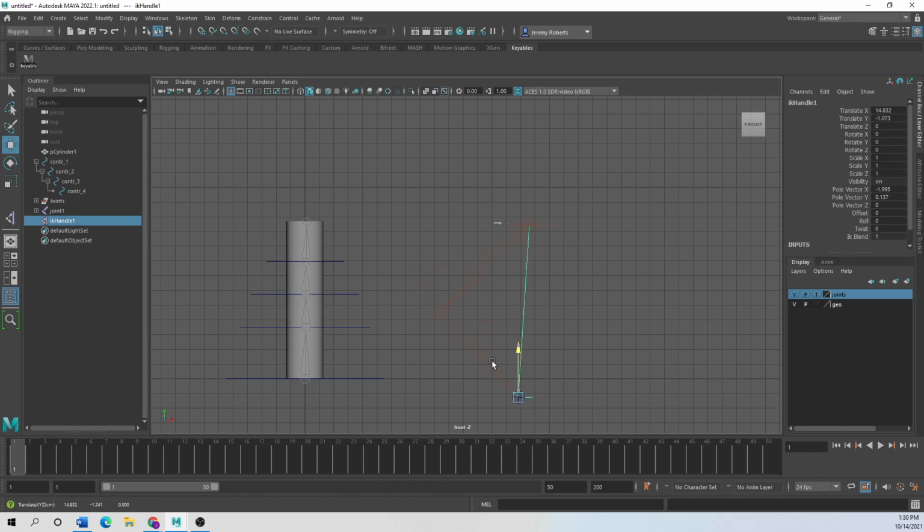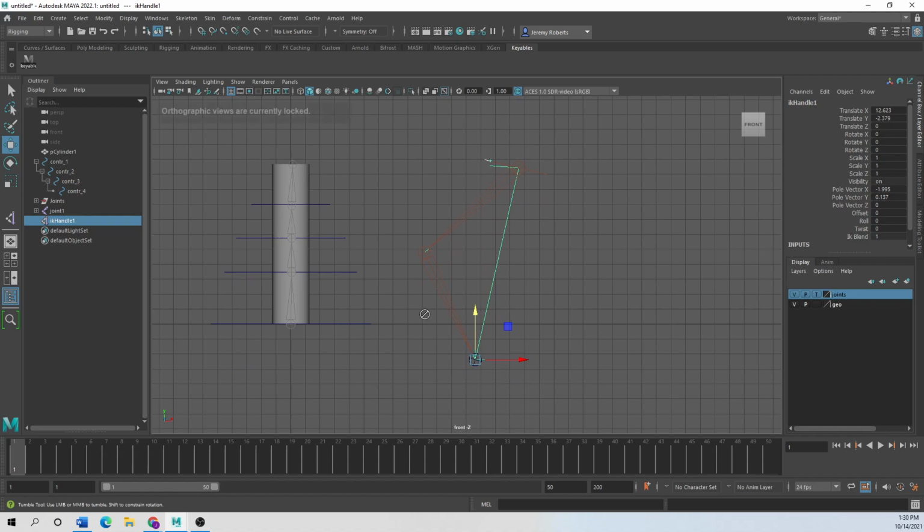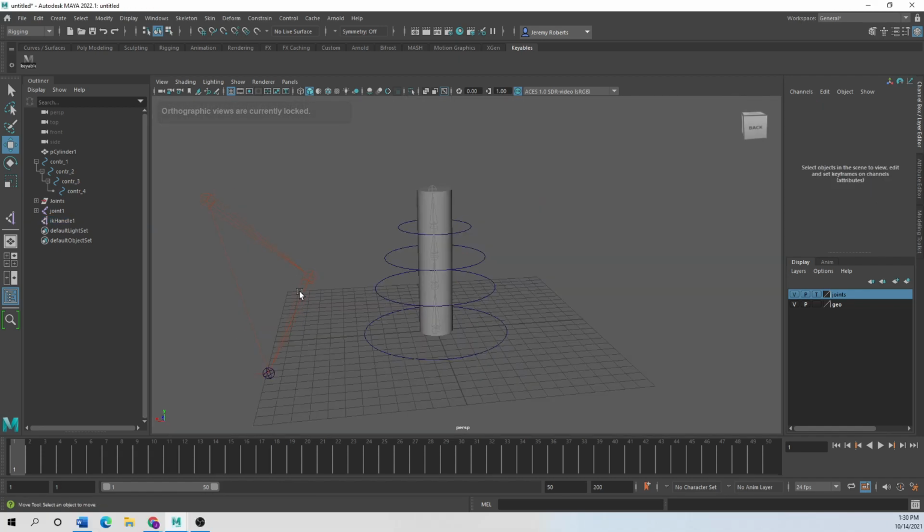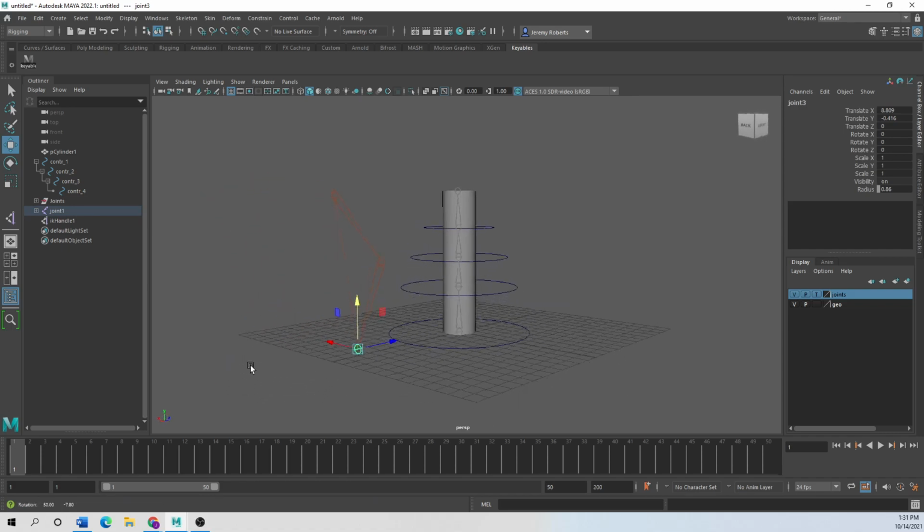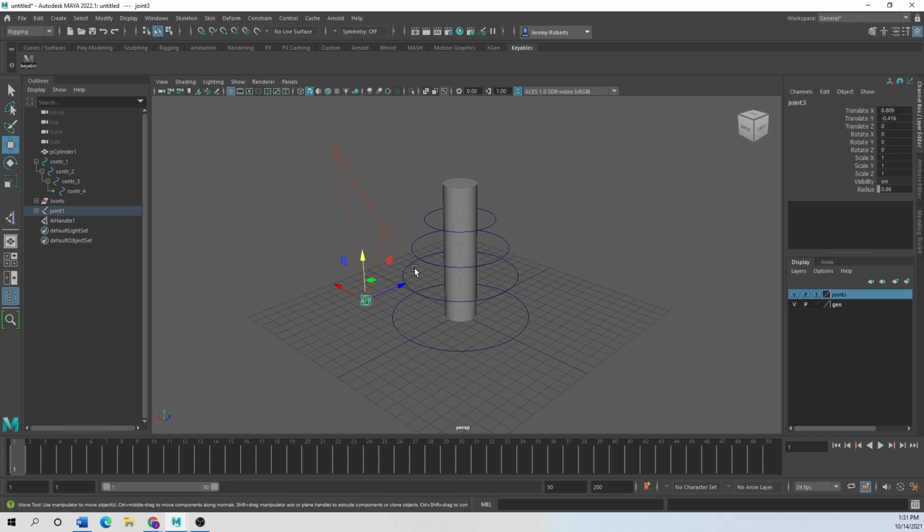This would be a definition of an IK handle, or an IK rig, where everything runs and then you set your controllers to control, say, a knee movement or a bat arm movement. This is a little bit more detailed, and we'll use these whenever you're doing any kind of humanoid. The way I like to rig up characters is I always run IK handles on the legs, and then I use forward kinematics for the spine and the arms. It's usually just easiest the way I do things. By researching, you'll find that people do different things, but understanding the difference between these two and how to use them is more power to you.